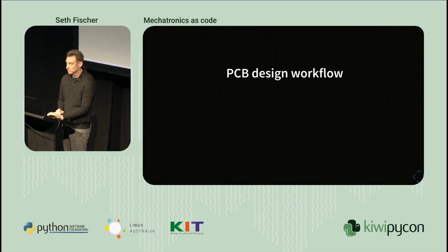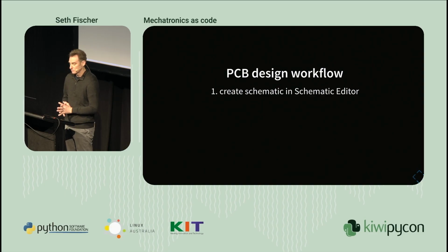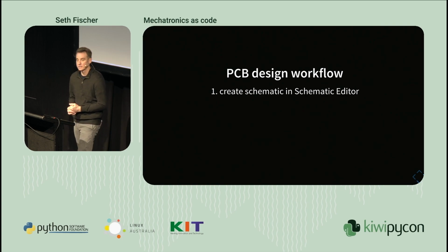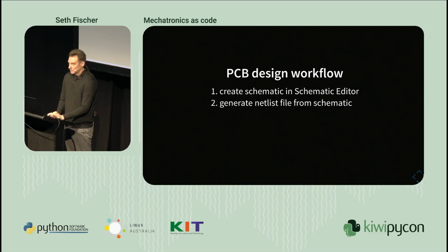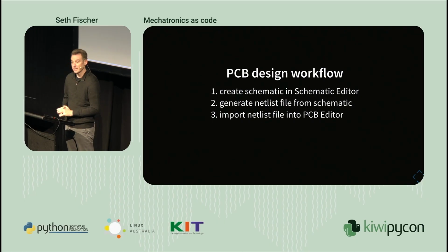Now first up, I will just give an overview of the PCB design workflow. First of all, you create a schematic in a GUI schematic editor. Then from that schematic, a netlist file is generated. The netlist file is imported into a PCB editor.